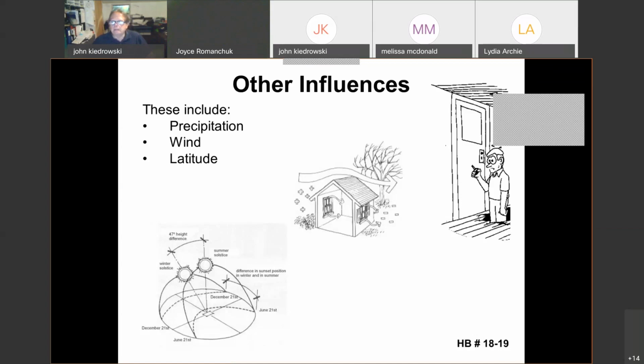So we looked at some of the issues, and certainly there are other influences when we talk about building science. So we talked about moisture, we talked about air, we talked about water entry. Certainly in this slide we can see other things we need to think about is how much rain do we get, which is, again, something that's addressed in the building codes, is how should we address issues such as rain. Should we have eaves troughs on a house or not?